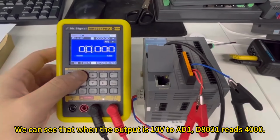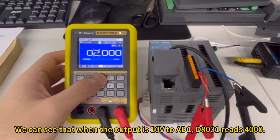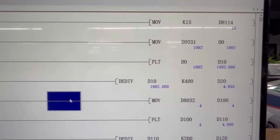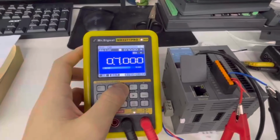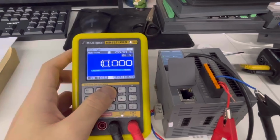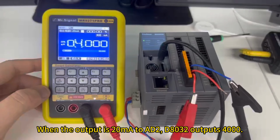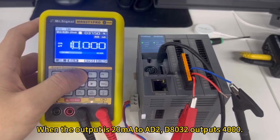We can see that when the output is 10 volts to AD1, D8030 reads 4000. When the output is 20 mA to AD2, D8032 reads 4000.